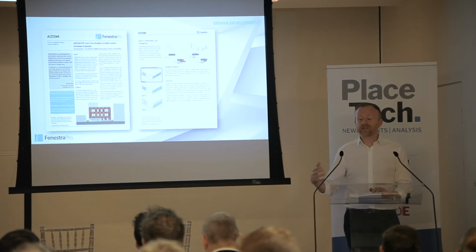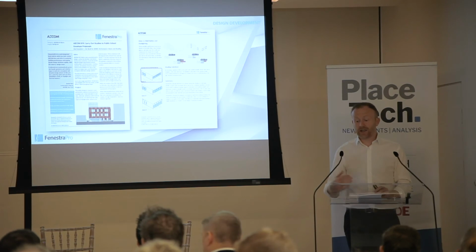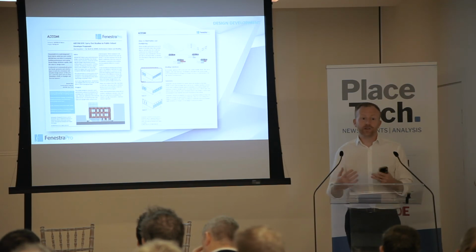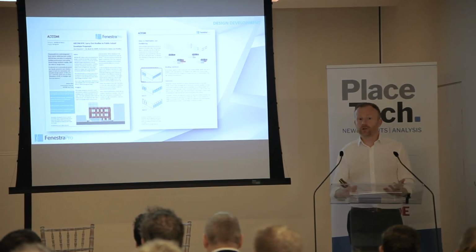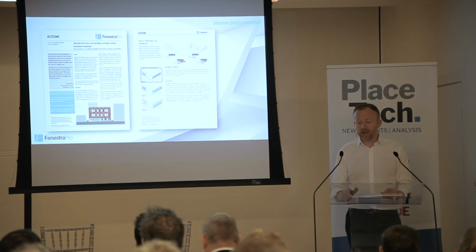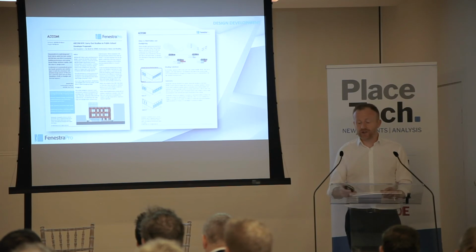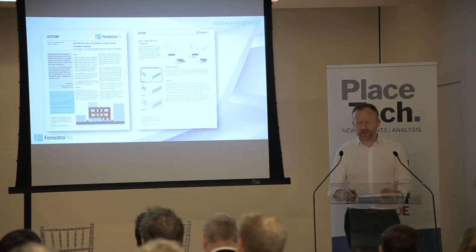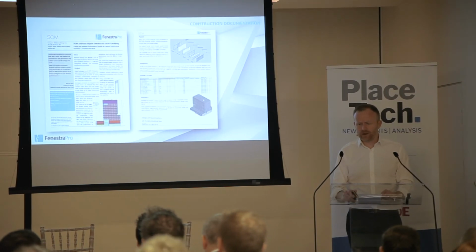But then as the design started coming together, a lot of that glazing was to the south. So again, they were able to start looking at shading solutions and different ways of managing those overheats, and what that would do to daylighting. I don't know if anyone's been involved in schools, but daylighting is a huge thing within classrooms, and what would their shading devices do to the daylighting? So again, just very quickly, a really good case study in terms of how quickly and easily they were able to execute it.